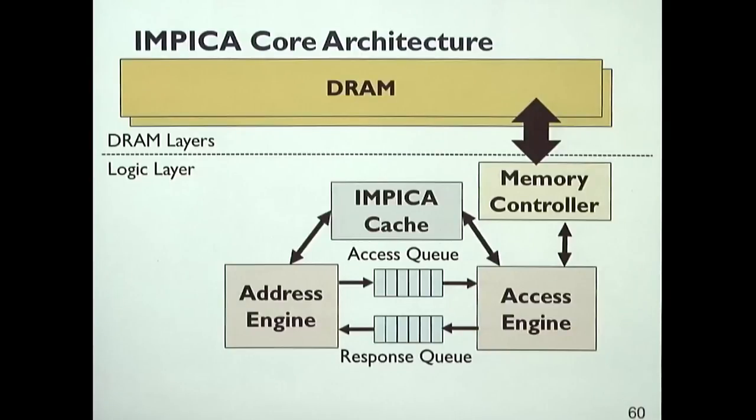So it turns out this is one of the learnings that we have had a lot, and other people have also had. Or maybe they didn't, but this is what we had. Basically, it turns out there's some locality here such that you can exploit. Even if you're doing operations inside memory, it's better to have a cache inside the logic layer, because that cache is much faster than accessing memory. Right? Because DRAM access is still a lot slower than accessing a small SRAM cache that's inside the logic layer. So it's better to have a cache over here and operate out of that cache.